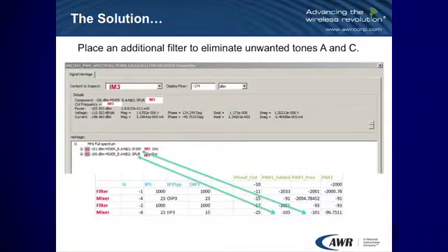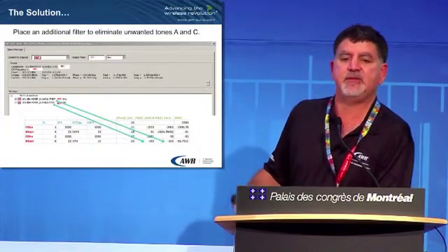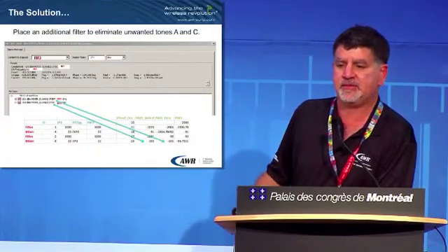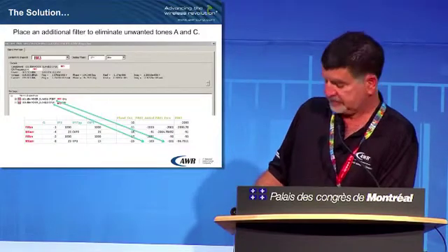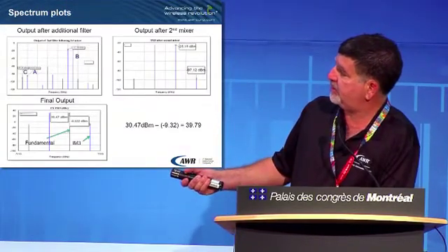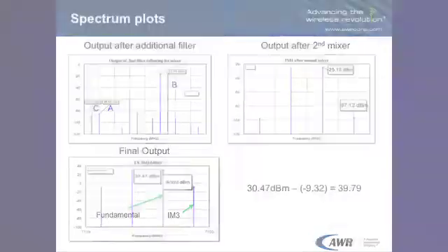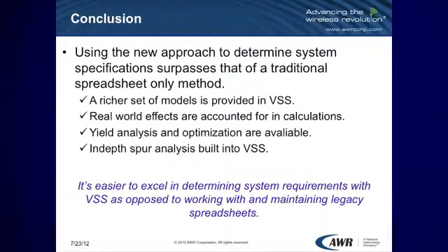If I'm really worried about that, I can dive into the minus 106 dBm and see what contributed to make a difference from minus 105. I put a filter. I chose to reduce one of the tones, or actually two here. We make the measurement, okay, and then we get the same results as the Excel spreadsheet.